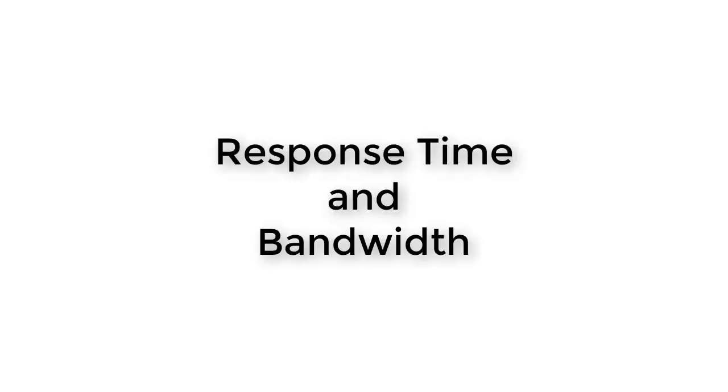The response time and the bandwidth of the sensor are both time properties. The response time tells you how long it takes for a sensor to respond to a static change in the input. For example, suppose that you would start with your potentiometer sitting still at a particular angle, and then you suddenly move it to a different angle and leave it there. You might not want to write your code to read the voltage output instantly. You might want to put in a little delay between the movement and the reading. The longer the response time of the sensor is, the longer you will want to wait between the move and taking the reading.